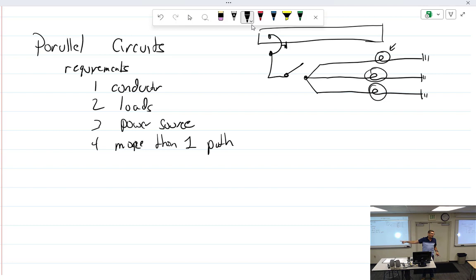if the power wire had a problem, the problem is usually it eats through a piece of metal or something. Then what do we have? A short, and a short usually results in fire, or smoke, or a circuit breaker pop, because you're taking too much of a load.